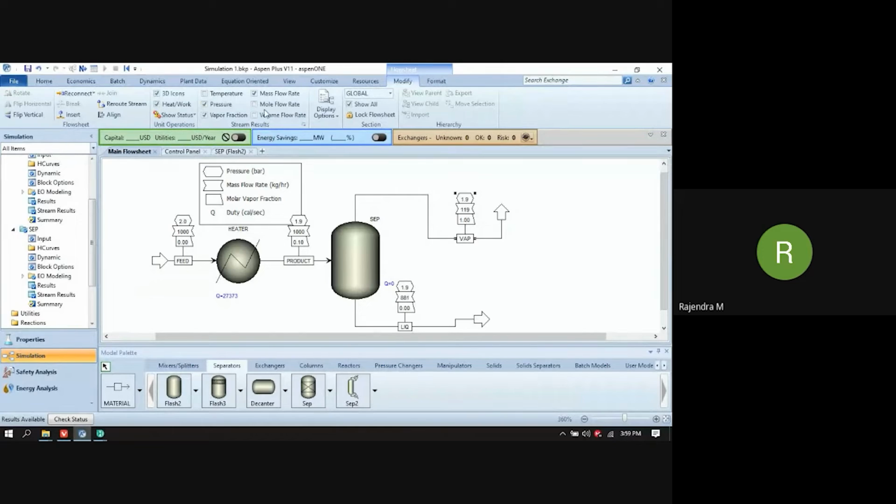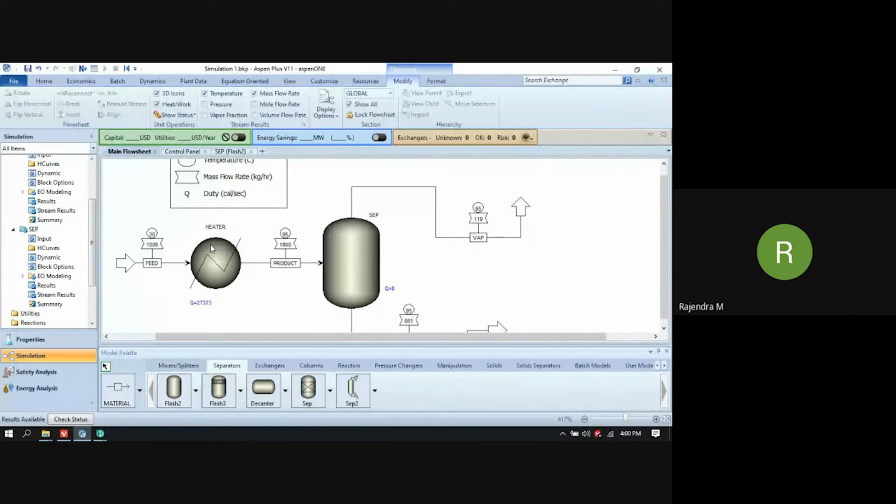And you can look at the temperatures. I will remove this. You can look at the temperature. So the temperature is no more 70 degrees Celsius. After changing the phase, the percentage of the phase became 10%. We have the vapor fraction, and the temperature of the stream is 95. Temperature is 95. The pressure is the same. Here the inlet and two outlets have the same pressure. Only the temperature has been changed after the heater.